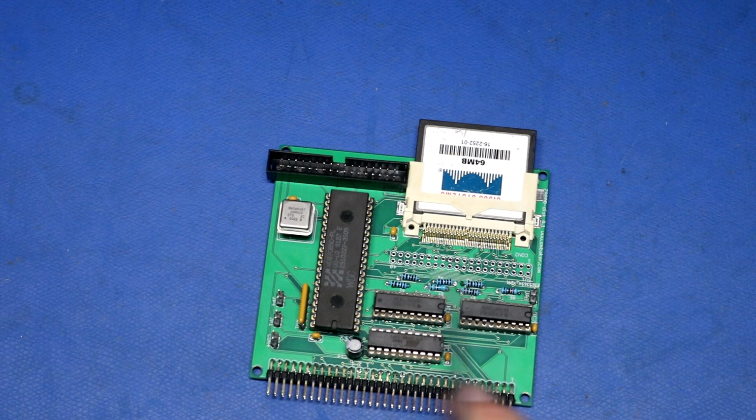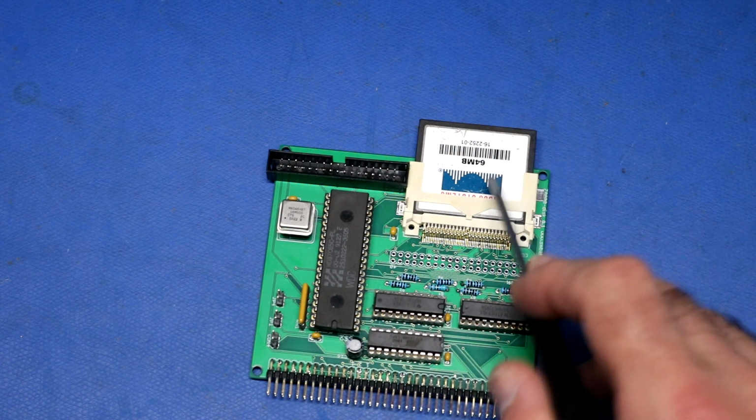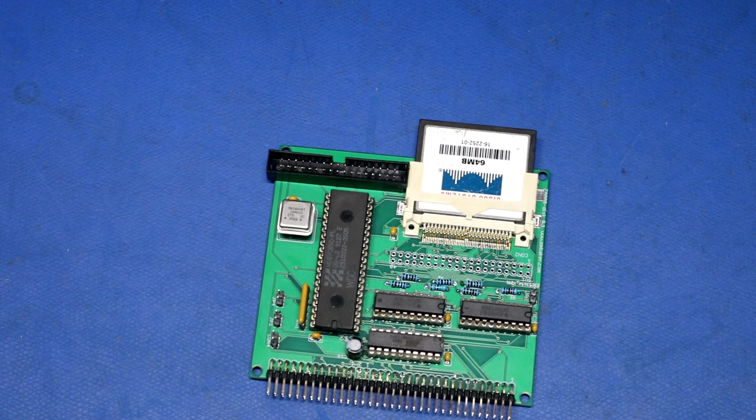Now down here are the two 74HCT245 buffers. Probably only one of them is needed because we're operating CompactFlash in 8-bit mode anyway. Super simple to interface a CompactFlash card. That's why every retro computer project has CompactFlash. Over here we've got the floppy controller, a WD37C65 chip, which I have used in several RC2014 projects, as well as in a Raspberry Pi project that was quite popular. That chip is here.